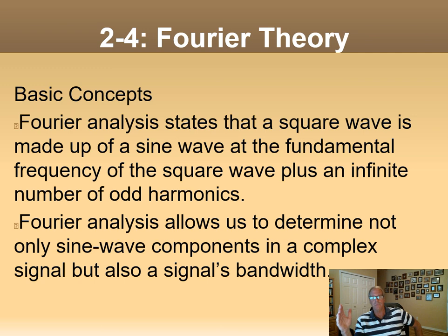So a 1 kilohertz square wave becomes a 1 kilohertz sine wave if you put a low pass filter on there that filters out everything above 1 kilohertz. You've got rid of the third, the fifth, the seventh, and everything all the way up. And that's pretty common to do: turn square waves into sine waves.